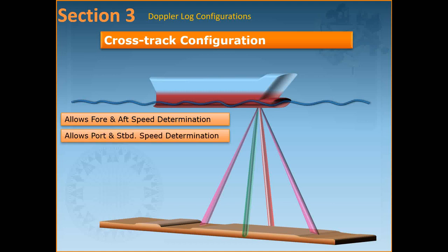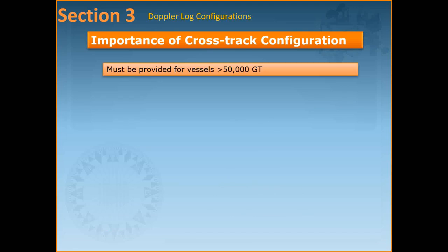The cross-track speed is particularly useful when it allows the integration of two separate speed vectors to get a much more accurate measurement of the ship's movement. Knowledge of this movement is particularly important and useful in general navigation, especially with sophisticated navigation computers which control course keeping very accurately to minimize steaming distance, time and fuel. Particular navigation as practiced by surveyors, exploration, seismic vessels, rig tenders and dynamically positioned vessels. It's also useful for pilotage when in strong currents and when berthing, particularly very large vessels, especially of more than 50,000 gross tonnage.